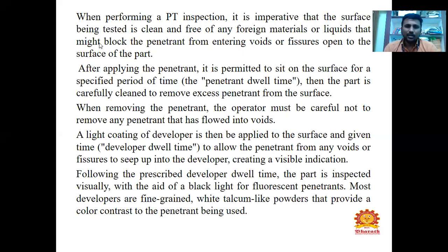A light coating of developer is then applied to the surface and given time. The developer's dwell time is the time given to allow the penetrant to come out of any voids and show up in the developer, creating the visible indication.